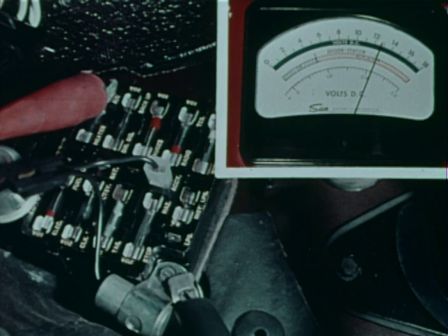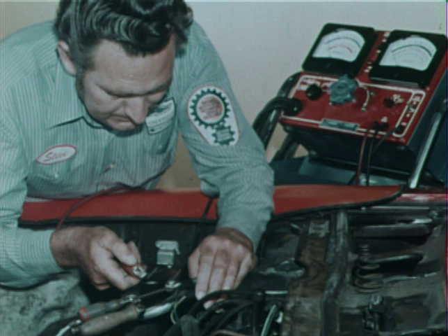With the current flowing through the circuit, that is, with the clutch engaged, no component should register a voltage drop greater than 1/2 volt. This is done by connecting the voltmeter across each component while the electrical connector remains intact.